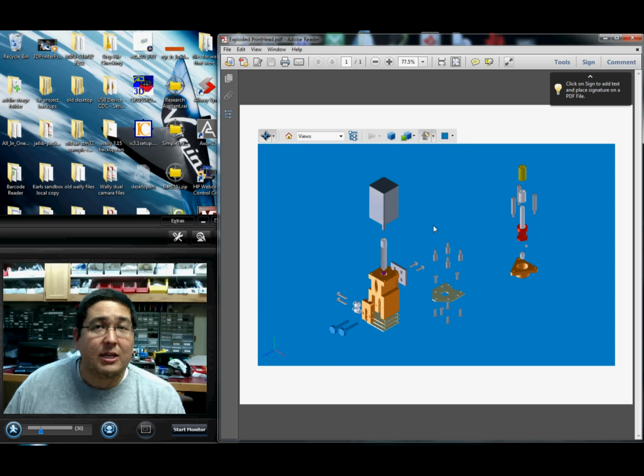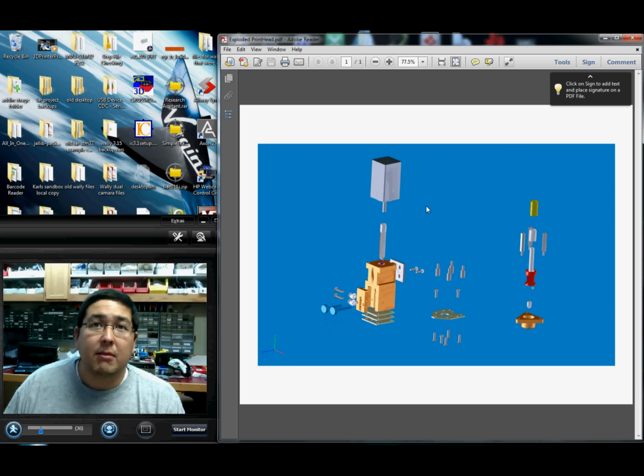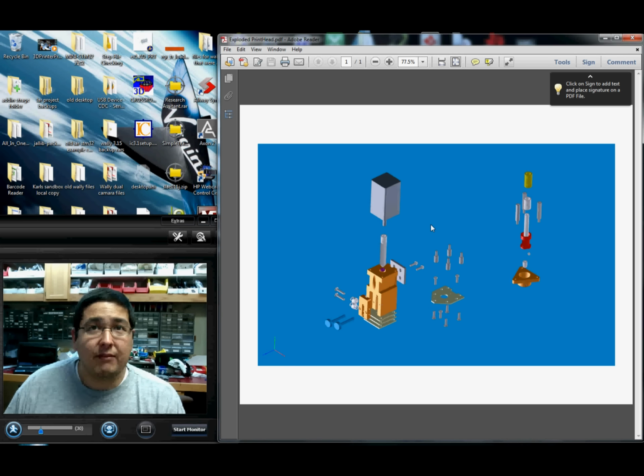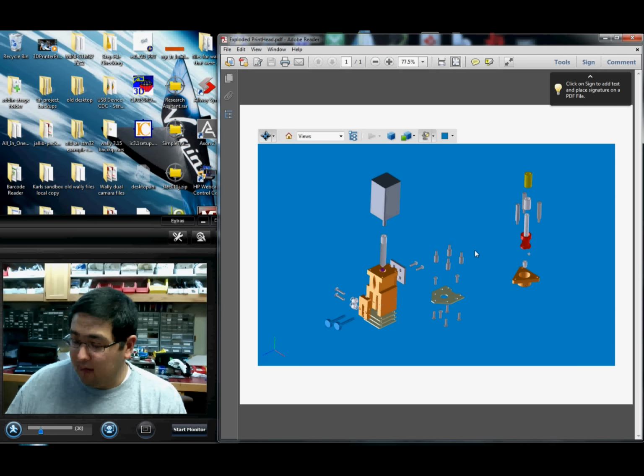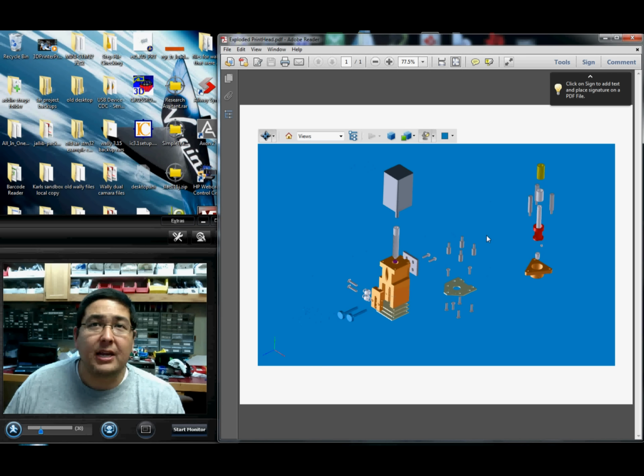Anything that you've created in CAD, you can put into a 3D PDF, as long as your CAD modeling software allows you to export it. From here, using your main clicker, typically a left click, you can turn and rotate the model. In this case, we have the exploded view of our extruder head. If you use your left and right mouse buttons in combination, you can pan to any location.